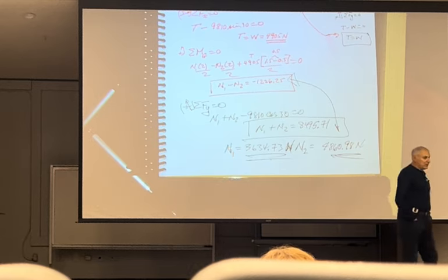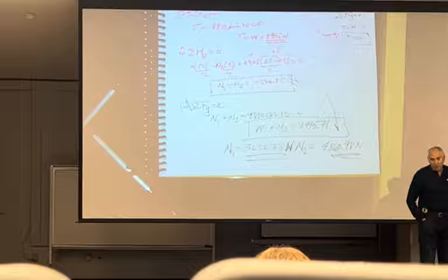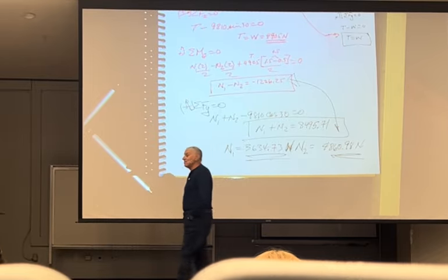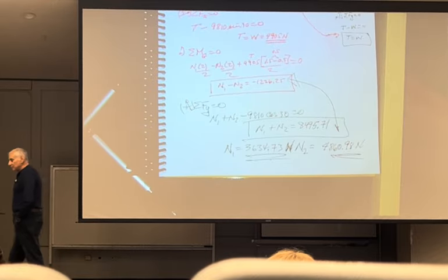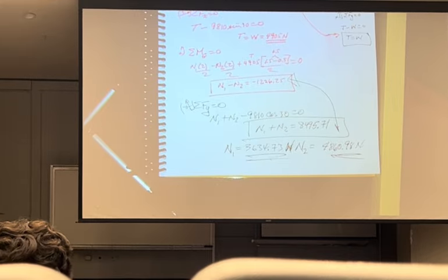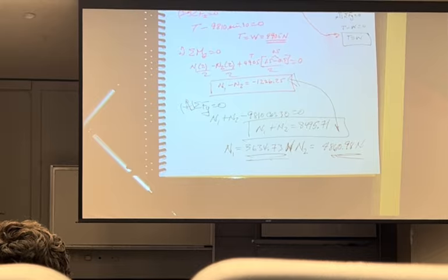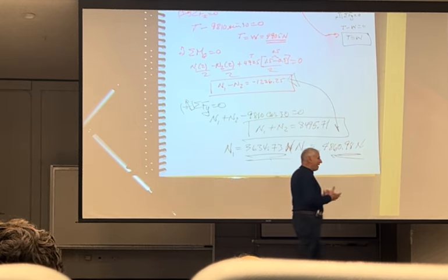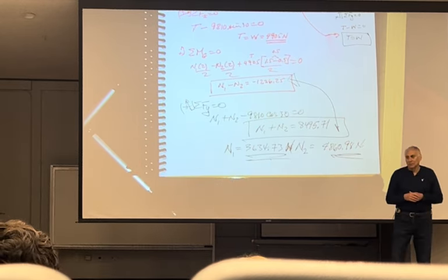Best thing you can do for yourself is take a moment right away when you're doing equilibrium of a rigid body. And you want to take a moment which eliminates as many unknowns as possible. That's the key. You can take a moment anywhere you choose to. However, I chose to take it about G. I didn't get a value. I got an equation, which is fine. There's nothing wrong with that. But usually when I write a moment, I'm looking for an answer. I didn't get one. I got an equation. Okay?